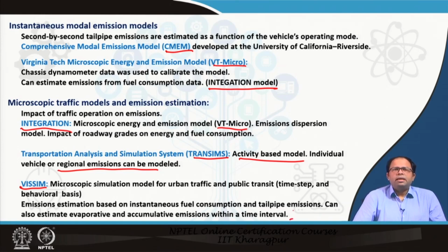So VISSIM is pretty robust in estimating the simulation for traffic in particular areas like we have discussed earlier, and with these emission factors, and if we can give the data for different vehicle fractions traveling in that particular traffic stream, we can also estimate the total amount of emission generated because of those movements. So this is how microscopic traffic models are nowadays being utilized for measuring emissions.